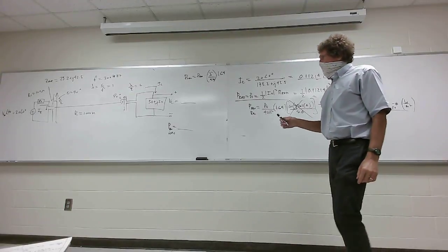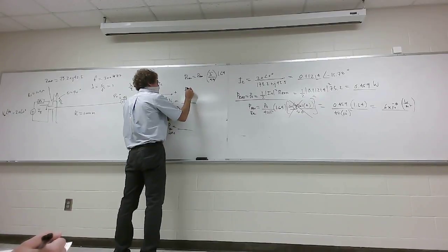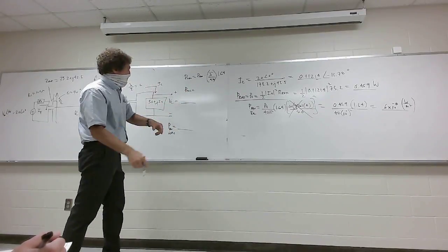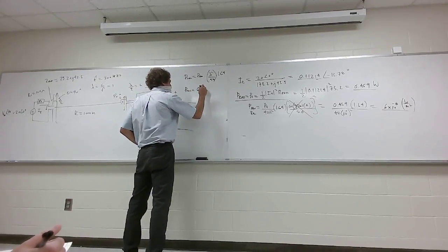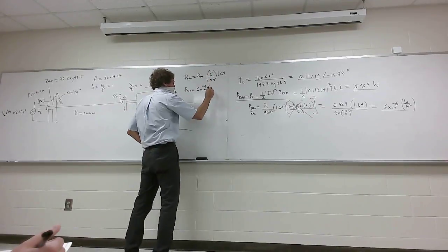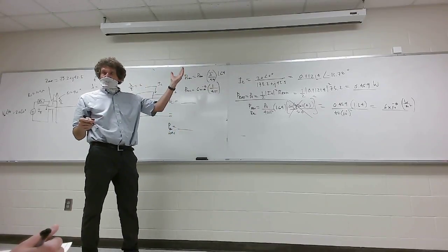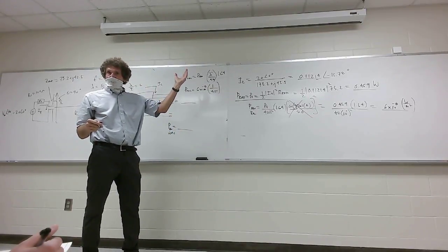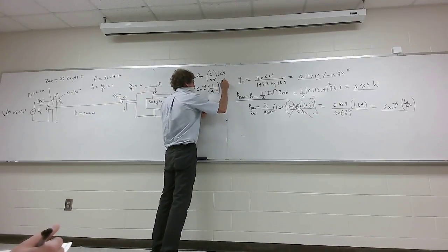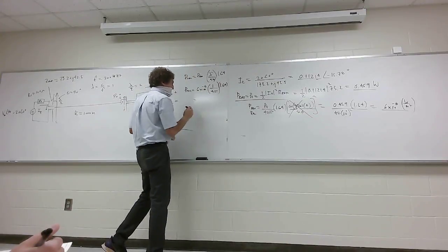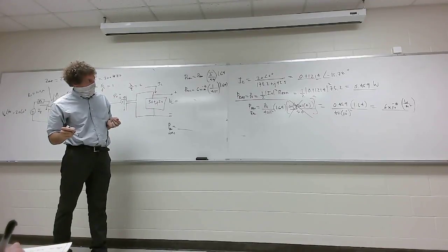So now the actual receive power that I'm going to use is the average power density, that's 6 times 10 to the minus 8 watts, times 1 over 4 pi, times the gain. Again, the maximum gain or directivity of a half-wave dipole is 1.64. It's at 90 degrees, it is the max, right? So now I find out what this is. And you can give me that number if you don't mind. What is that? 7.83